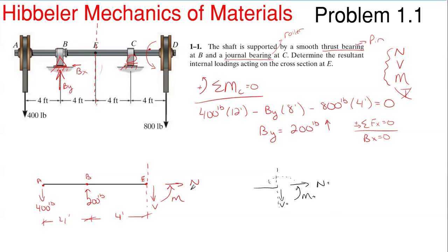So what we're doing is we're just writing these out in the positive form. It makes it a little bit easier for our final answer because internal forces are usually given without arrow directions. The arrow directions aren't going to make a lot of sense because when you take the other side of the cut, the right side, your arrows will be flipped. It will look like a mirror. So arrows usually aren't used. We use positive sign conventions here for internal forces.